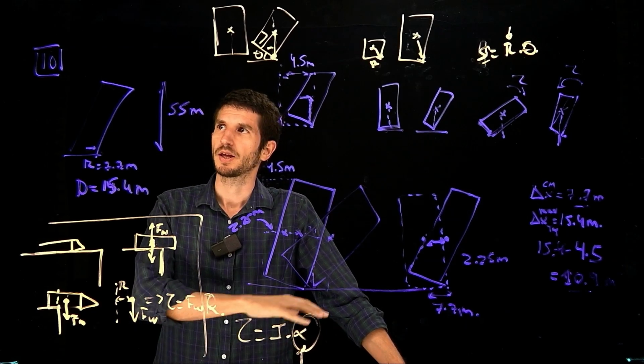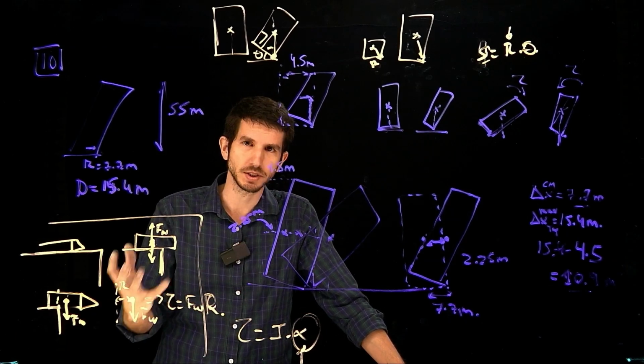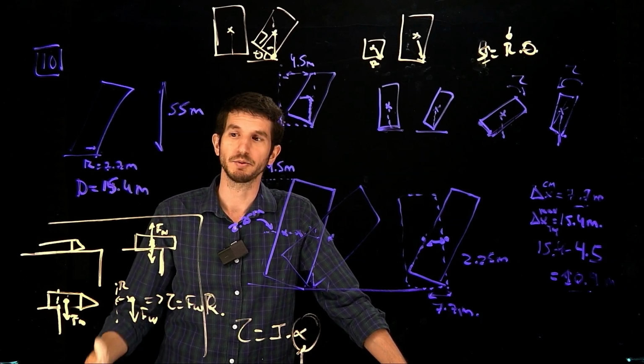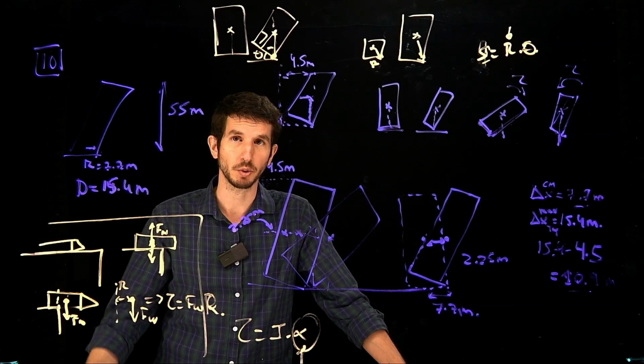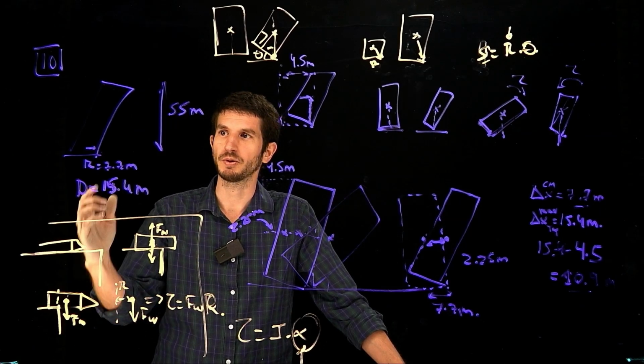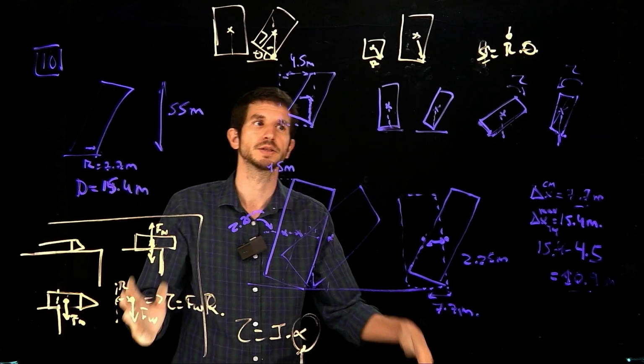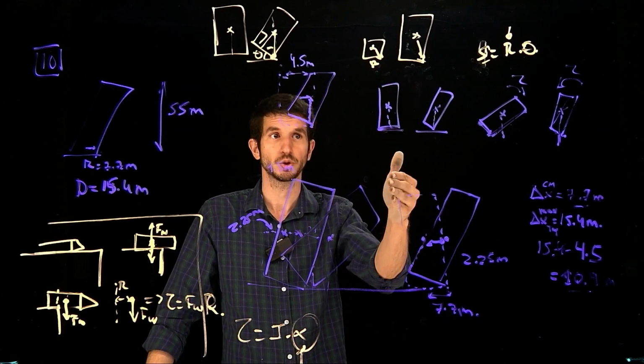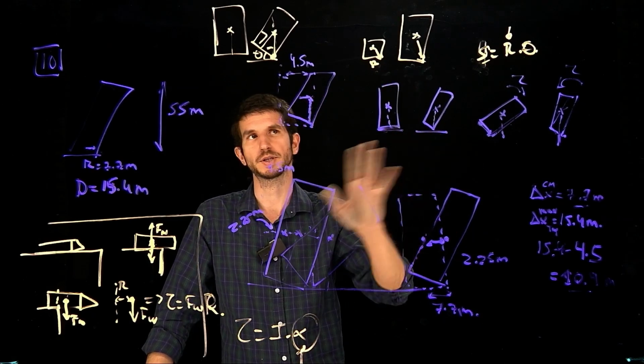So we saw how solids deform, what the ultimate reason is microscopically, and also how solids are in equilibrium whenever there is no net force and no net torque. If that is not fulfilled, it's because maybe the center of mass is displaced. So we understand stability. If the line falls out of the base, it's going to tip over.